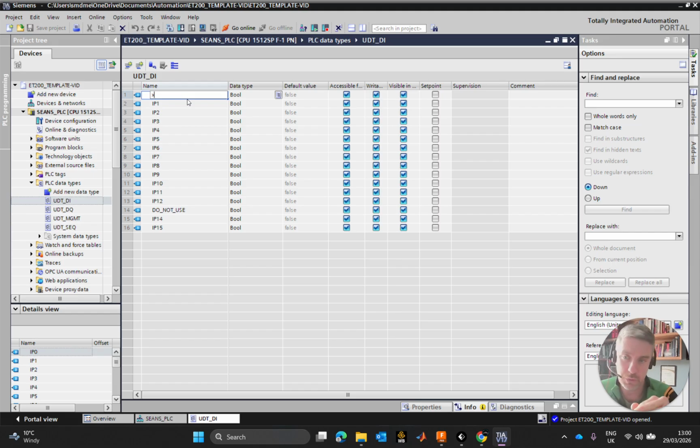So in IP0, this is the nomenclature I use. I use an X to identify in code that this is Boolean. I use L for limit, 0 for zero limit, fully retracted limit, i.e. zero distance, cylinder A: XL0A. Next one, XL1A. Now, why do you start with retracted before you start with the extended limit? Well, from my perspective, it makes sense to me to read from left to right. So when I'm looking at a profile plate, everything that I try to teach and promote has a left to right flow, unless it's specified otherwise in the circuit requirements, where you might have to extend vertically or otherwise. But other than that, always make sure your flow goes left to right.